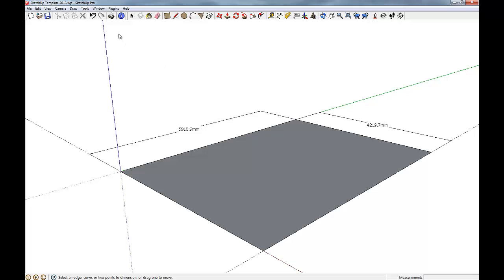The other thing that you're able to do in SketchUp accurately is both create and measure angles. So for example, if I put a line from this point here over to that point there, and we go to our next tool, which is our protractor tool. We click on that point to get the protractor.